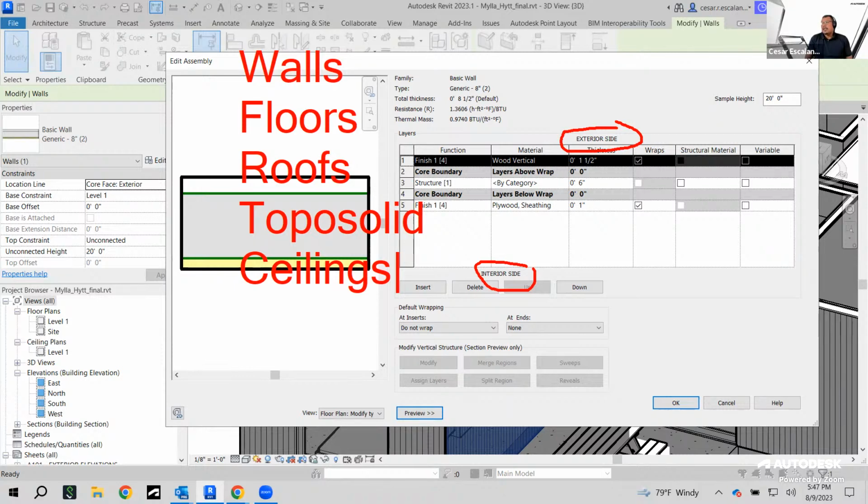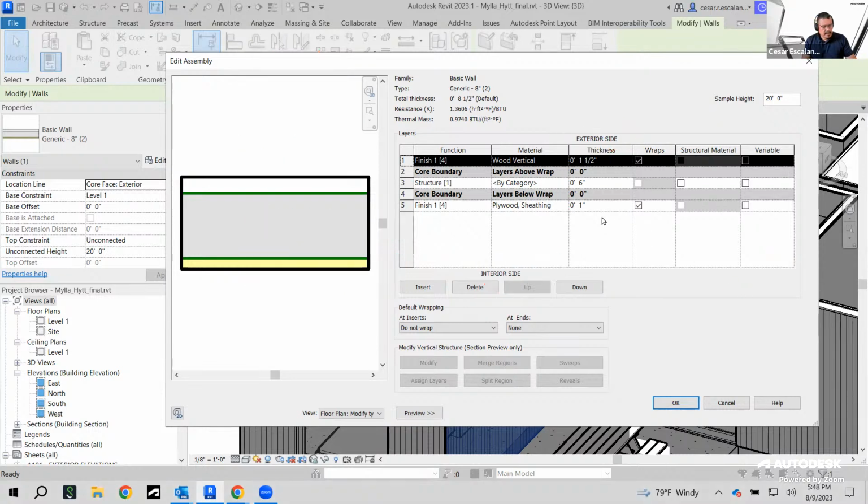And you cannot save them as external files. And each of them can be represented using this system of layers using this similar dialog box. One of the things to point out is that Revit also keeps track of mechanical and energy properties that can be associated with the assembly, including the total thickness, which is the sum of all these values.